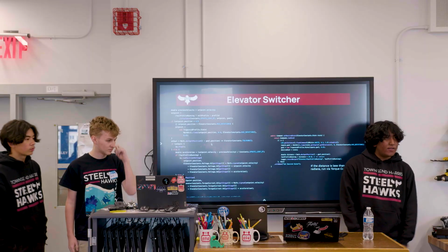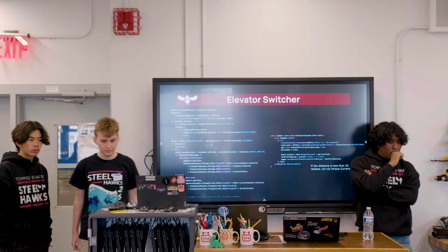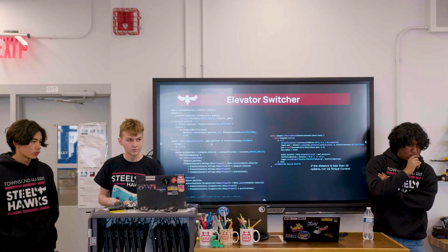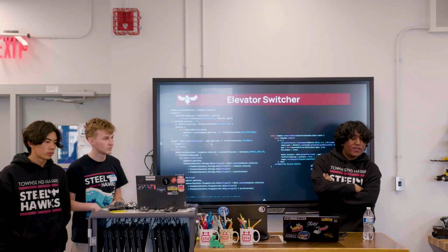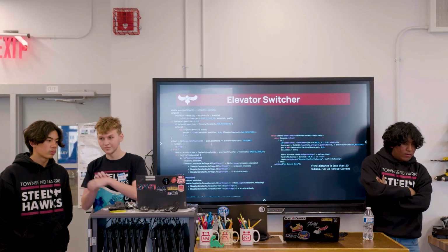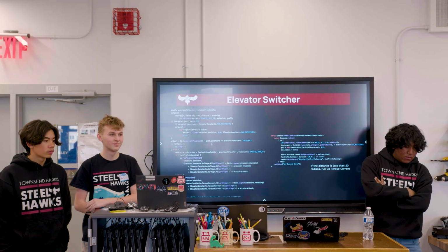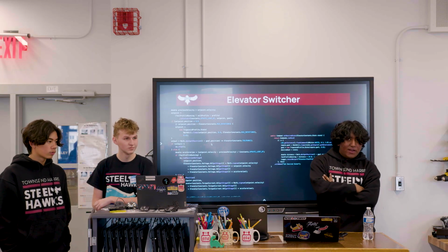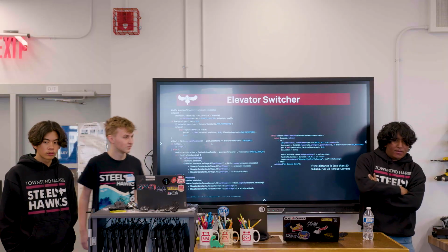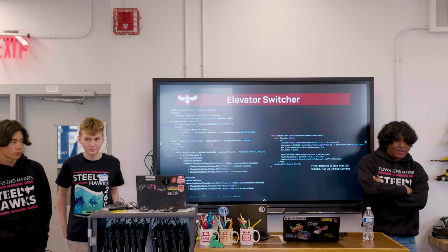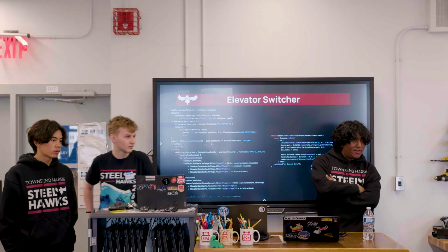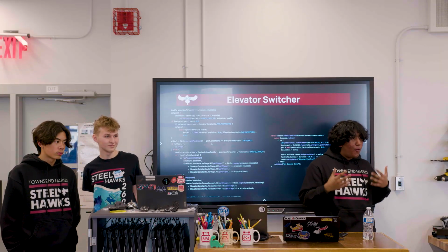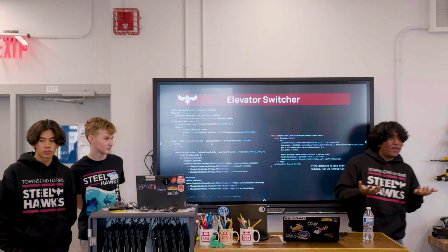Right? Any other questions? To clarify, when you're using both trapezoidal and torque current, you have to tune your elevator twice now. Yeah, you do have to tune it twice. And was there ever a time the mechanical group made a change to the elevator, and then you have to go back and retune both of those again? Yeah, both. It is more work, but I will say, tuning is just something that your software team should be good at. You gotta drill it. I actually think it helps them because you're forcing them to do it more times. You're basically just drilling it in their mind.